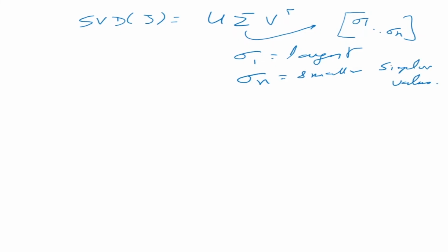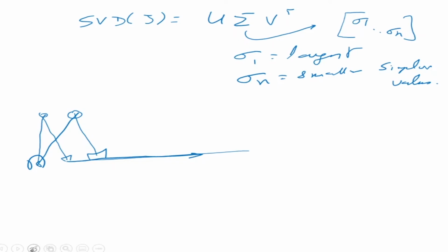Okay, so this is basically telling us the magnitude of the ellipse, the major axis, minor axis, and it is also telling us the direction of the ellipse. So when we look at this manipulator, let's look at this example. This is an interesting example: suppose you're moving in a straight line like this. So I'm going to move this manipulator in a straight line like this. When we are somewhere here, my manipulator is like this, and the direction of my ellipsoid is going to be like this. We can find this out.